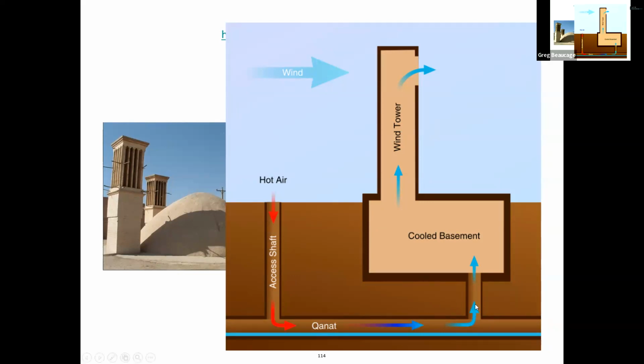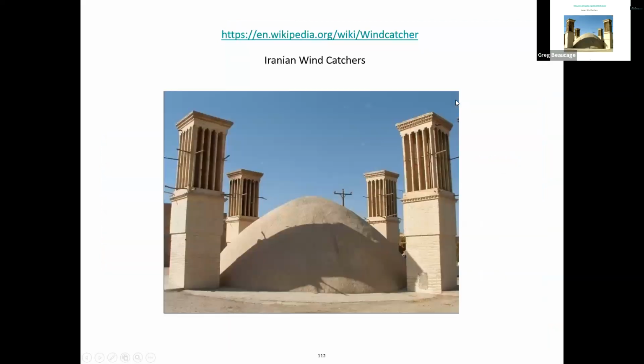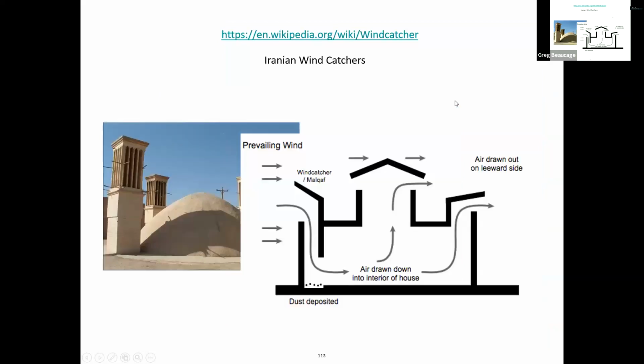And they run through the cities. So they don't have air conditioning there, and it's a dry atmosphere. So you have this kind of evaporative cooling. Like the wind, the hot air blows over the qanat and up through the house, makes it humidified. And then at the top of the houses are these wind towers that pull the air. And there's a prevailing wind across the desert. So you just kind of design this thing that way. Looks something like that, right? It's kind of like a way to design air conditioning architecturally.